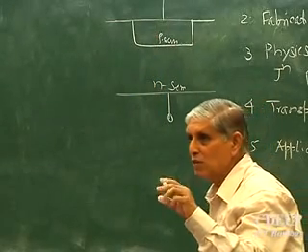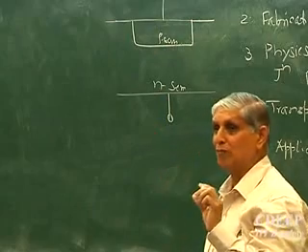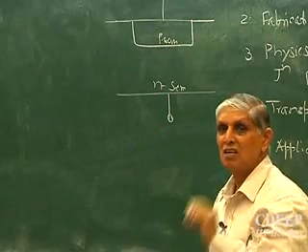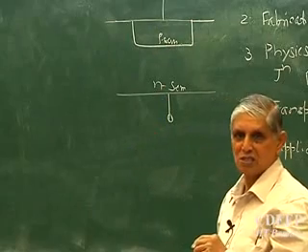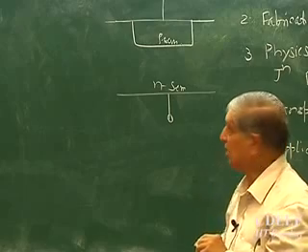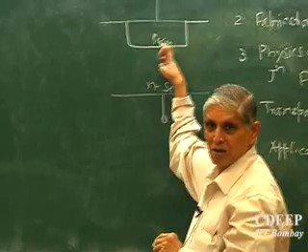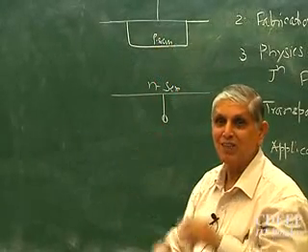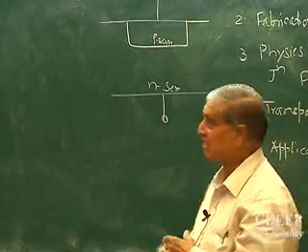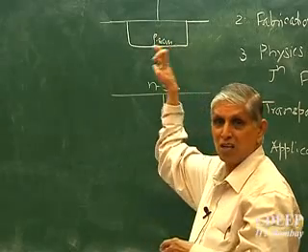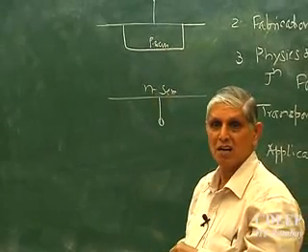So another word I use is contact. I need contact to the p region and contact to the N regions. Is that correct? This is the fab requirement. What is the first thing? I must be able to introduce impurity. I must do it in a selective area, I must do that process. And then I must make contacts to both P and N.